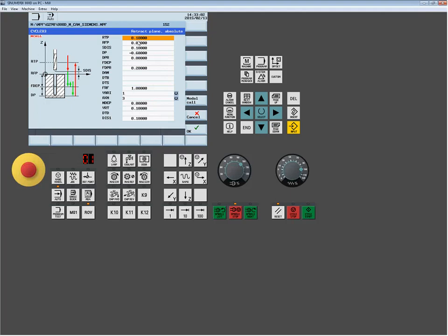So then I would just simply go through the actual resulting cycle and validate that it's all correct, that the depth was in the right field. Because if they built the placement wrong when they post it, like, oops, we were off a position, so we put the drill depth of 0.6 right here, one place down, so now it's affecting a reference plane, or maybe I moved it up and all of a sudden my drill depth is under my safety distance field. Those are the things that are going to get mistaken initially when you're first building a post processor.